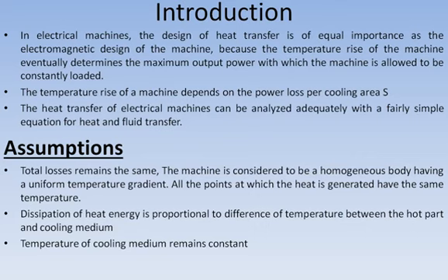So it is actually the temperature rise in electrical machines which is determining the maximum power at which this machine can be run continuously. So now you can understand the significance of temperature rise in electrical machines. In fact, it is this temperature rise which is determining the power rating of the electrical machines.